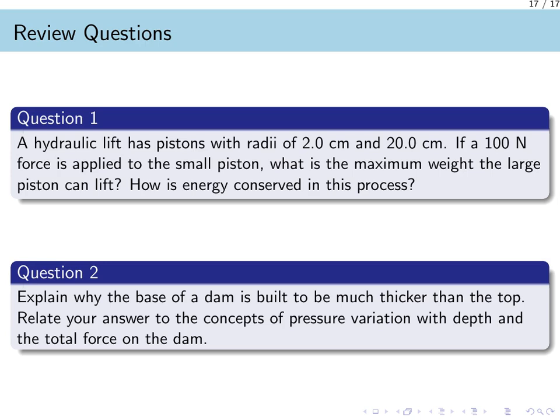Think about the work done on each piston. While the forces are different, the work done must be the same, which means the distances the pistons move are also different.